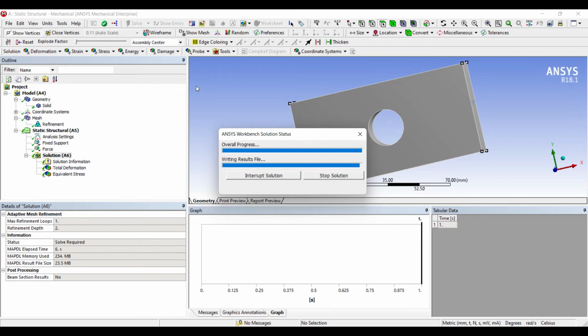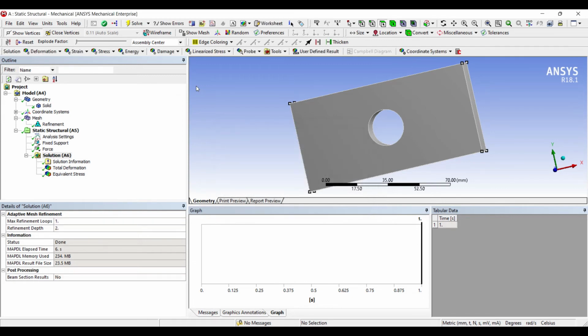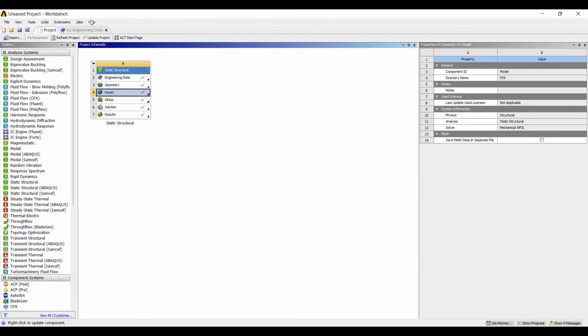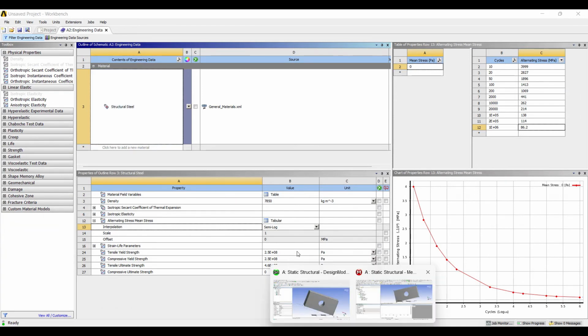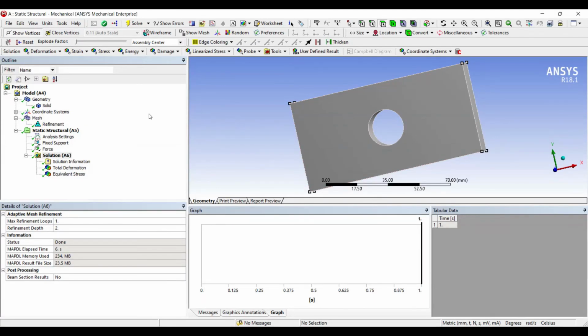If the stress generated is less than the maximum stress it can endure, it means my body is going to be safe with the number of cycles that is predicted, that you saw here. So these are the number of cycles that the body can work for, or these many number of times you can keep on applying the load and removing the load, and the body will sustain with that load, 10 kilonewton.